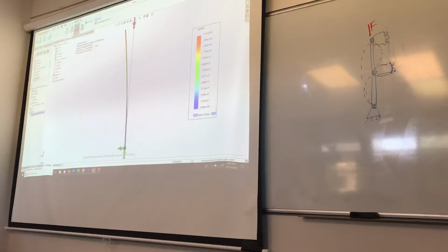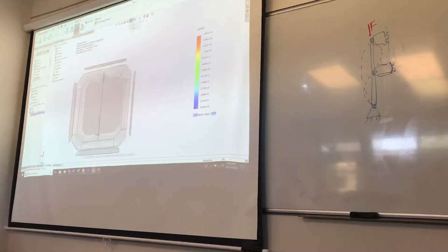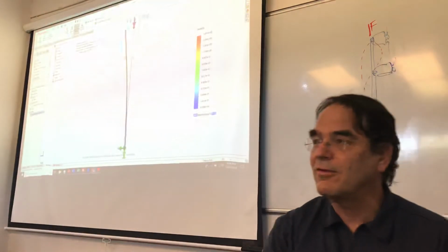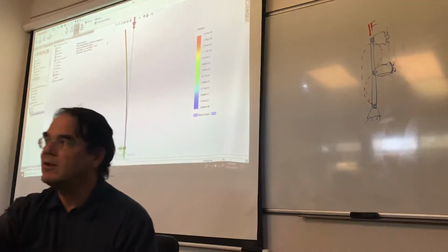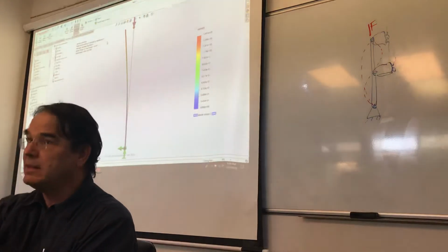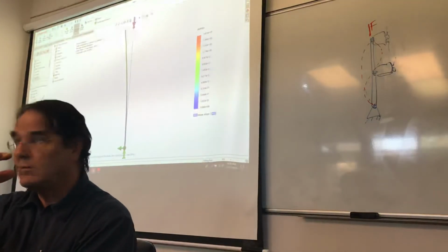I got the same mode, but when I go to the other direction, I have to look at the other plane, right, over here. I still have the same mode shape, but now my load has gone up to 34,000 pounds. What's happening is because it's asymmetric, it wants to bend in the same fundamental shapes, right?